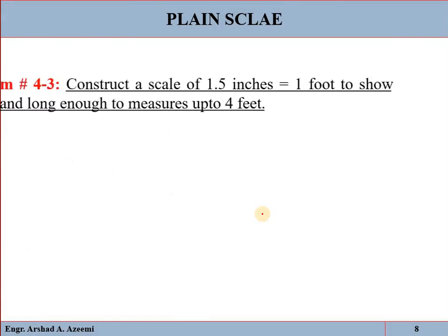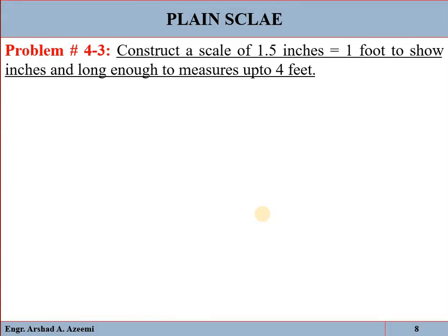Okay, now we have example problem 4.3. Construct a scale of 1.5 inch is equal to 1 foot to show inches and long enough to measure up to 4 feet. Okay, so see, the engineer's scale is given. First convert it into representative fraction.